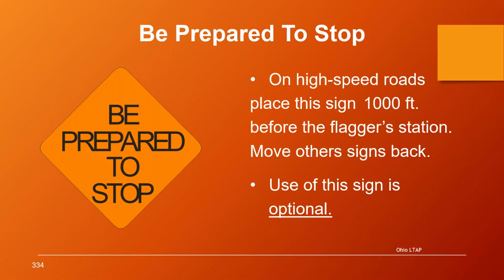And then if you're working on a high-speed roadway, 45 to 55 miles an hour, we want you to include this sign in the mix. It says, be prepared to stop. So we would put this sign in advance of the flagger symbol sign. And of course, the sign says the use of this sign is optional.